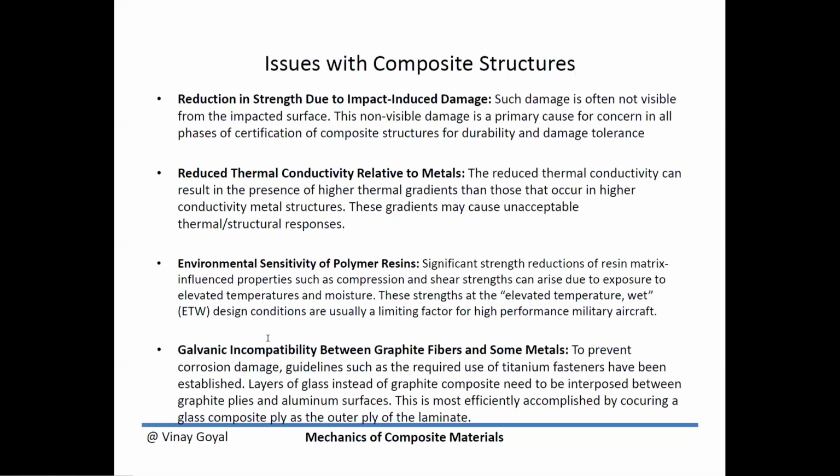For example, lightning damage can be more detrimental to composite because it's a more local type phenomenon, that it will damage the composite since the heating was not able to get dissipated through the conductivity of the material. So the heat transfer is not very effective in these materials.